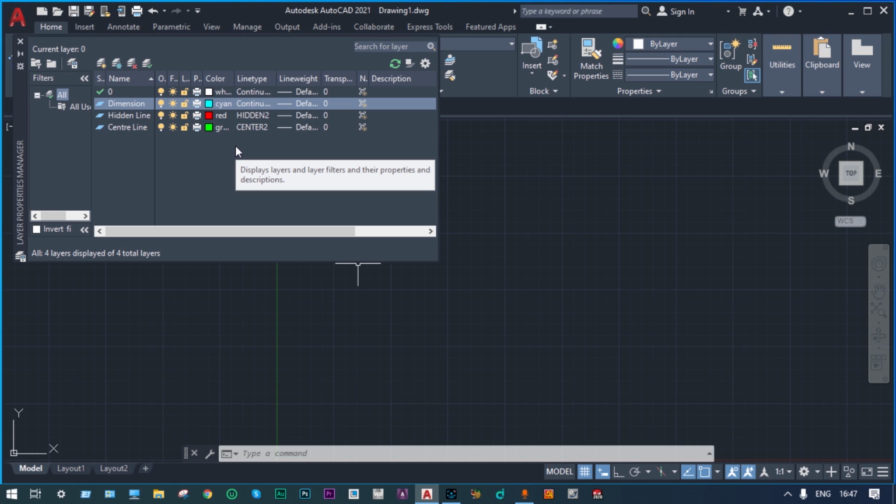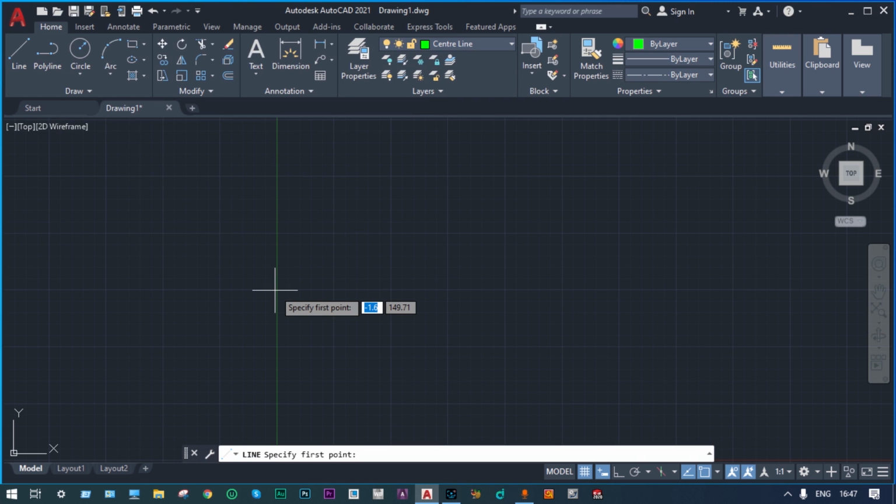Now with a basic example, we'll show how to utilize those things, and if required, we can hide these things also. Okay, so we're starting with the default layer. Now see, when you are making any line, orthogonal mode is off. Orthogonal mode means we can draw only 90-degree lines. Click here to get orthogonal mode on, or press F8 on our keyboard. Right, so orthogonal mode is on.